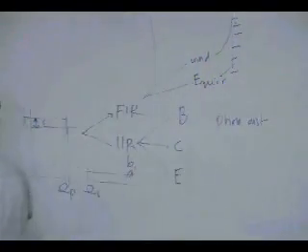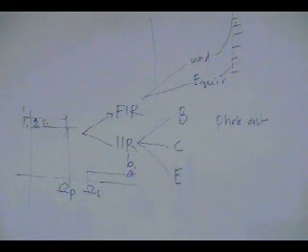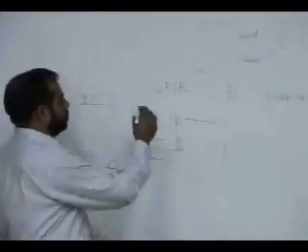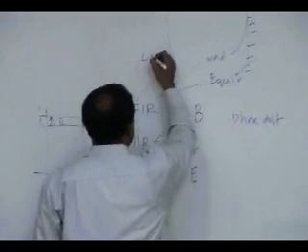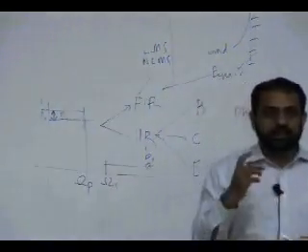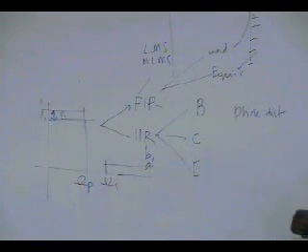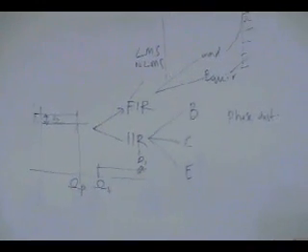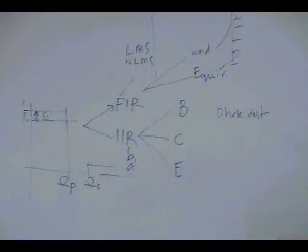Almost all equalizers are FIR filters. Though they need to be IIR, they are FIR filters. Especially in equalizers, you don't want to waste time figuring out the stability. So usually, if you go into adaptive filters, you will learn about LMS, NLMS, all these techniques, least mean square error. So you design FIR filters. You say you have these coefficients. The coefficients are changing all the time.